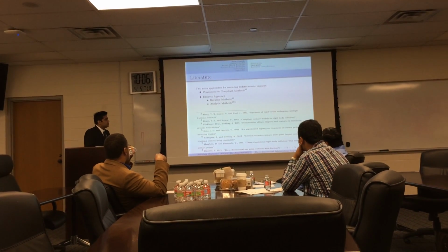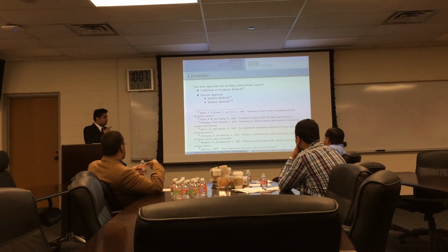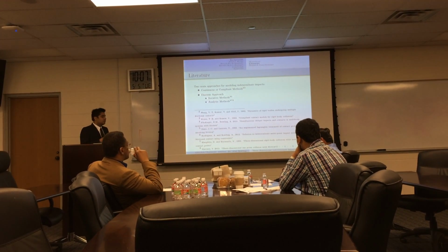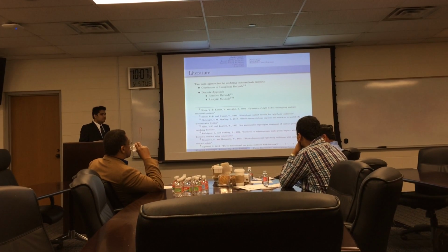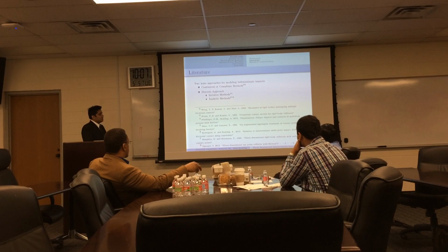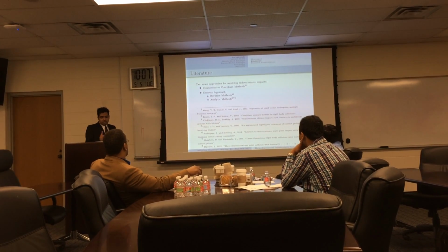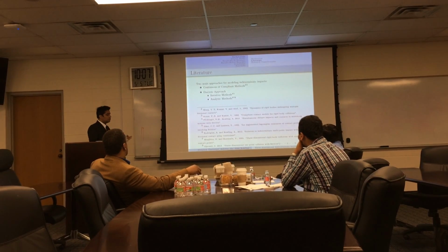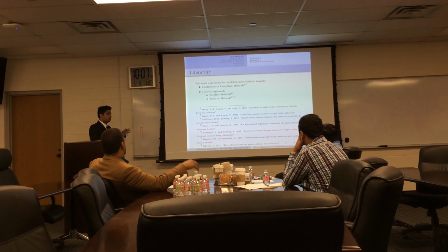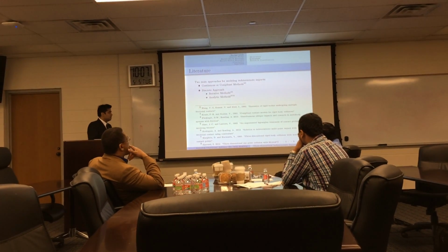In the analytic methods, the constraint forces are related to each other using certain parameters like the coefficient of friction and the coefficient of restitution. And in the 2-dimensional case, analytic methods usually convert the whole equation of motion into a simple algebraic equation, and that's why the name analytic approach.